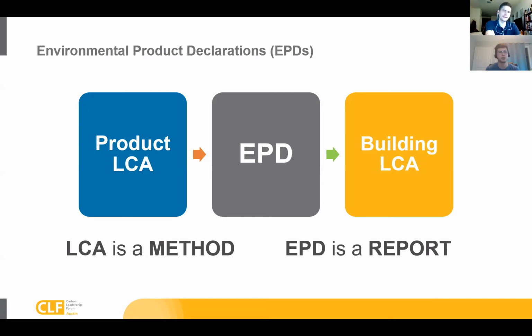Yeah, and we'll talk about this a bit later as well, but when we think about system reductions, so whole building reductions versus material reductions, EPD is just for a material. It's just saying for the concrete mix, or even an industry average, for 4K concrete in this area, this is roughly what you're looking at for impacts. But it reports those. And when we think about the different modules, most of the impact is coming from module A, the processing and manufacturing, and EPD only lives in module A. The assumptions for use, maintenance, repair, and then end of life are captured in an LCA, but that's not usually reported by an EPD.